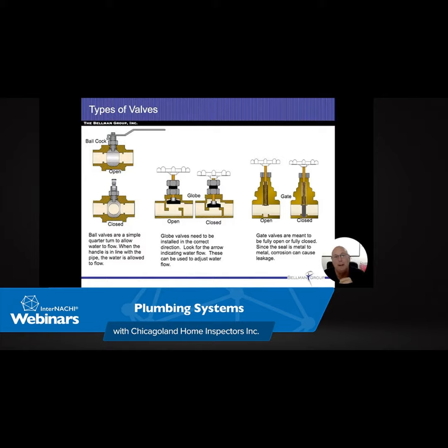And to keep them living long, I know one guy who's a water heater fanatic. He's got a 7-year water heater, and I think it's going on 50 years right now. And that's what he does. He just changes out that anode rod and that pressure relief valve. And they do sell hinged anode rods and thicker anode rods so that you can slide it in there and another piece will go in there and you can get the whole thing back in there and tied up on there.